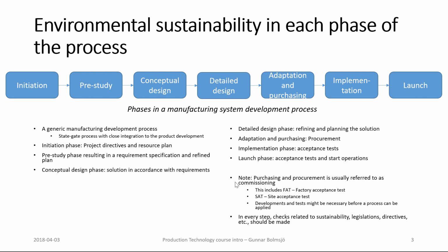And then there is a site acceptance test, SAT, that is done after the FAT is accepted. The whole system is taken down, transported to the end user, set up, and then there is a site acceptance test, and the whole thing is tested on site in a manner that is accepted by both parties. And usually, from a commercial point of view, after the site acceptance test is accepted, the final payment is done.